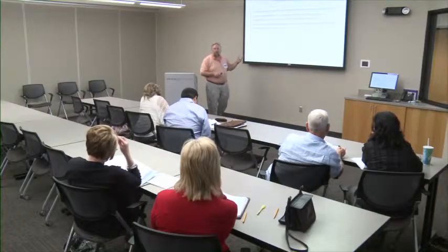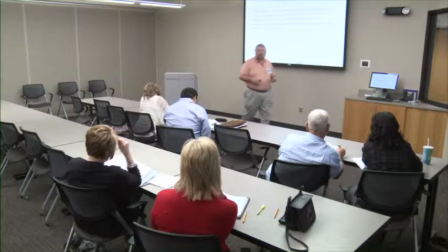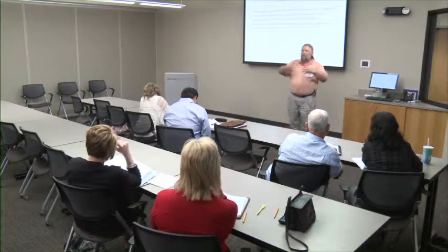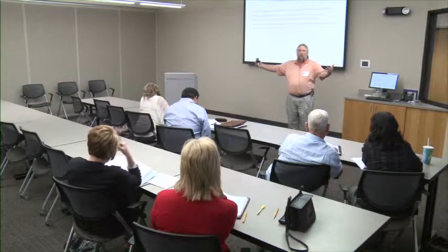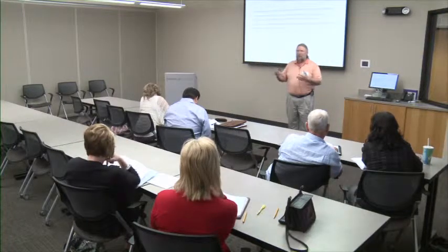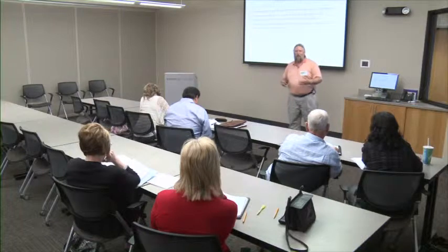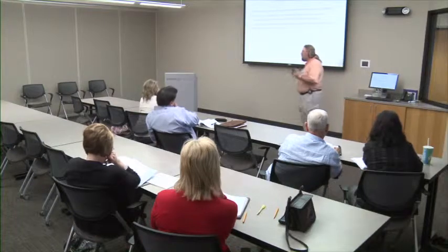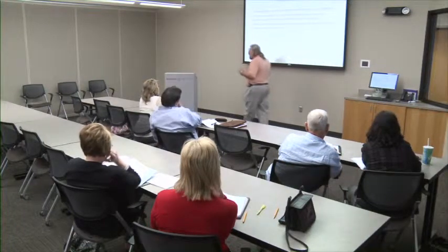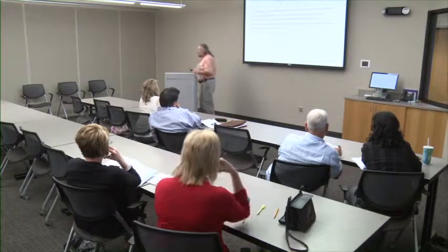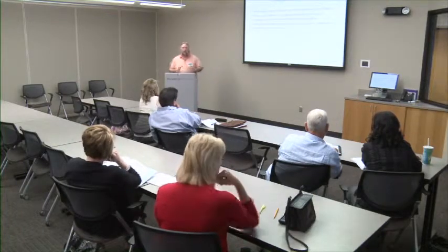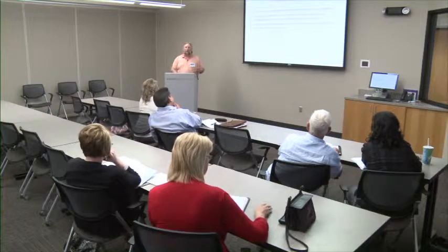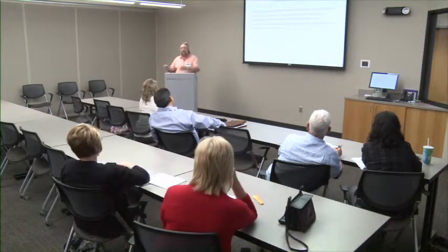It just basically gives us better detail for our planning. If we're talking just 4 different pieces, yeah, it's an easy schedule, but we really don't get to see how detailed it is or, if something goes wrong, where it went wrong. If we divide it into a smaller schedule, we get a better chance to look at it. Of course, on the reverse of that, if you divide it into too small a schedule, you're going to get caught down in the details. We don't need paint baseboard A, paint baseboard B, paint baseboard C. That may be too detailed.